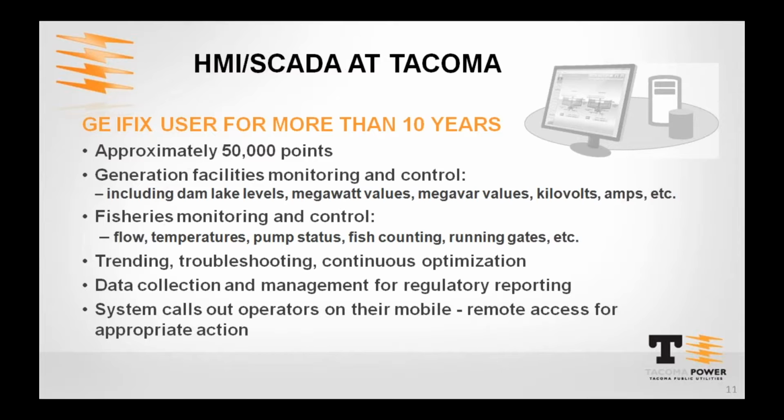The HMI system, particularly at generation, is a local control, and we have a centralized energy management system that we interface with. And so there's really two forms of control. One is the local HMI SCADA system that we're responsible for, and then there's a centralized system that interfaces through the SCADA to control our generation facilities.